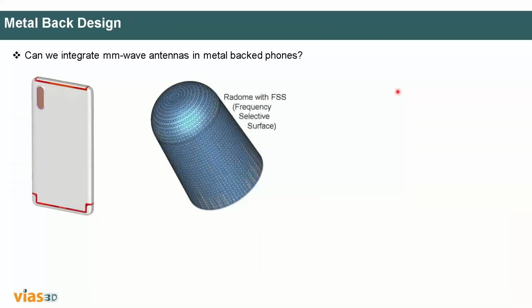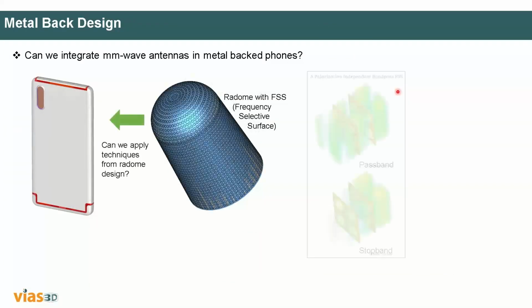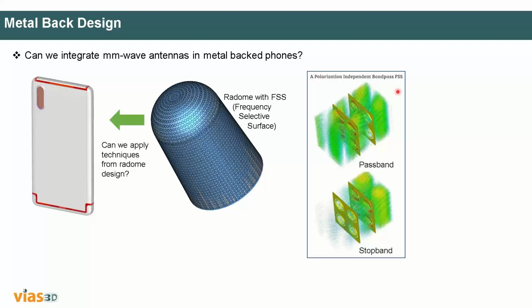So the other thing we can do, as I mentioned, is use an FSS structure. What is the significance of an FSS structure? Just like an antenna, you can also represent an FSS as a series of RLC chain. It contains LC components. Specifically, it is an LC network. Basically, you can say it is a filter, mostly a band pass filter. It will only allow a range of frequencies in and out.